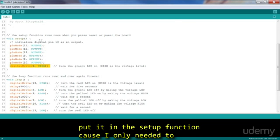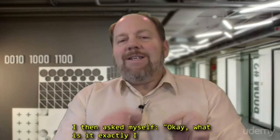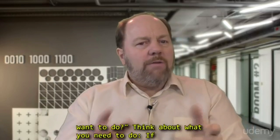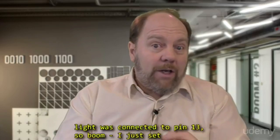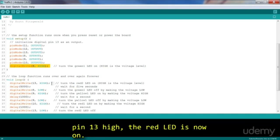So I put it in the setup function because I only needed to run it once when we first started up. I then asked myself, okay, what is it exactly I want to do? Now think about what you need to do. If the number 1 traffic light is green, that means the other light needs to be red. Well, the red on the other light was connected to pin 13. So, boom, I just set pin 13 to high. The red LED is now on.